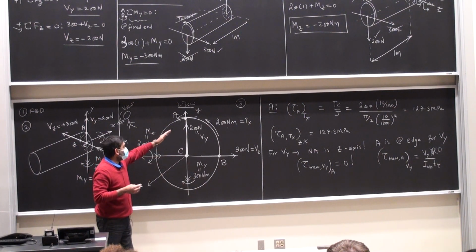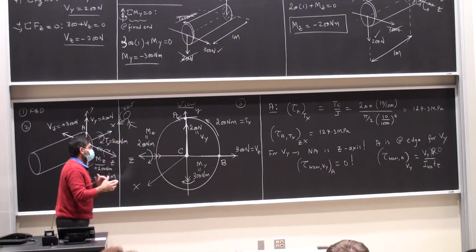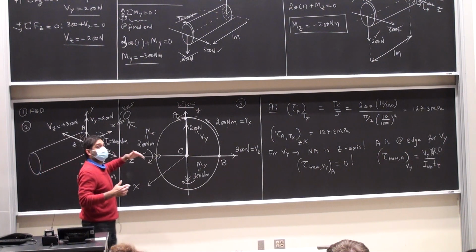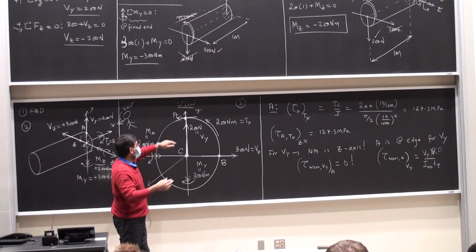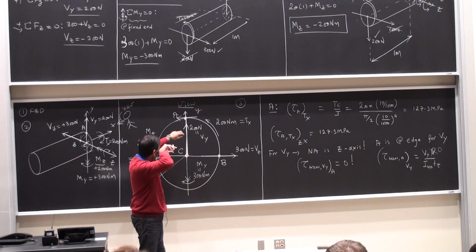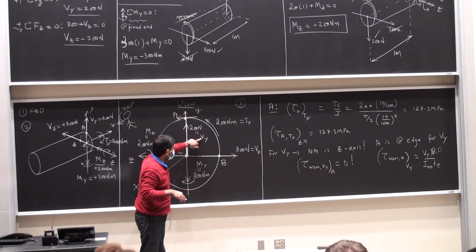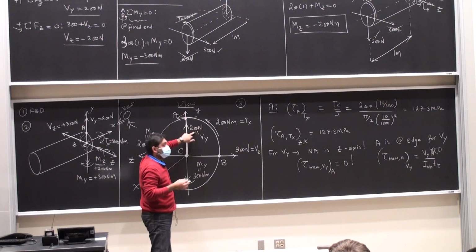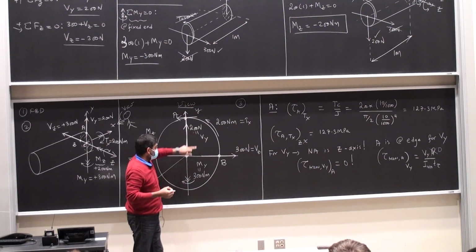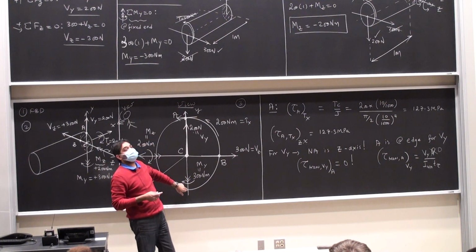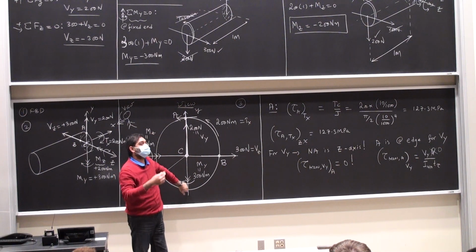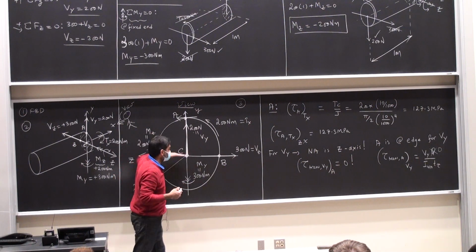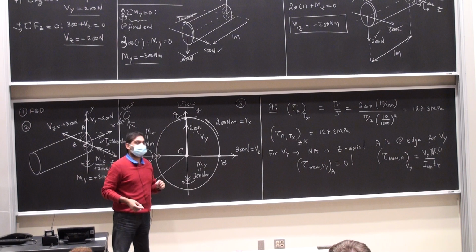And the axis that is perpendicular to the shear force is considered to be the neutral axis for that particular shear force. Because you see, precisely for this particular reason, if I calculated the value of the shear stress at the point A based upon this, I get 0. If I calculate it at this point, I will also end up getting 0. And the value of the shear stress is going to be the largest at that axis.